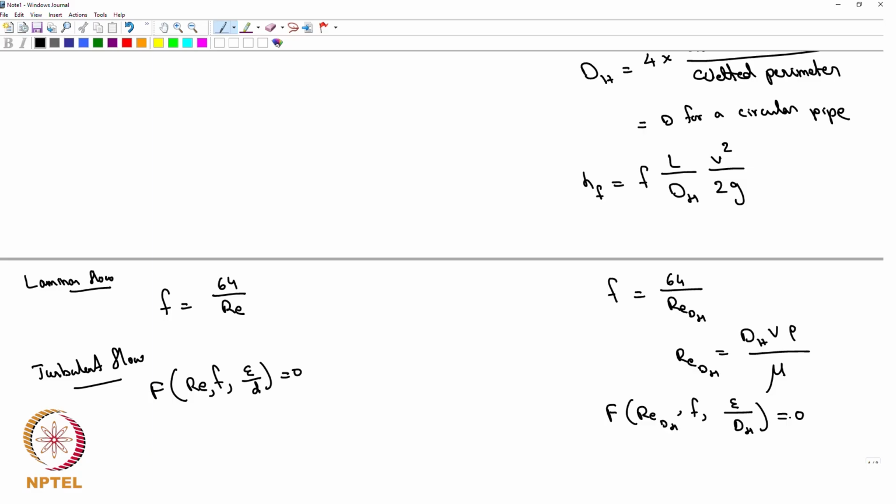If you have wondered how good it is, for laminar flow this relation is found to give you an error of 40%. Huge. For turbulent flow, this relation seems to give approximately 15% error. Of course, it depends on what kind of geometry and so on. So these are definitely not good relations, but we do not want to do elaborate calculations for any other geometry. Just use the same framework. Questions?